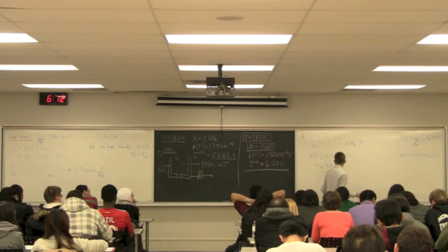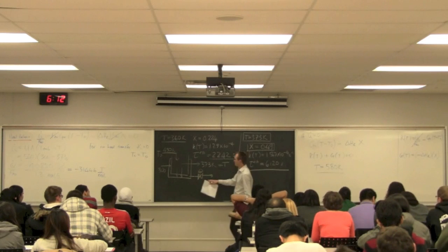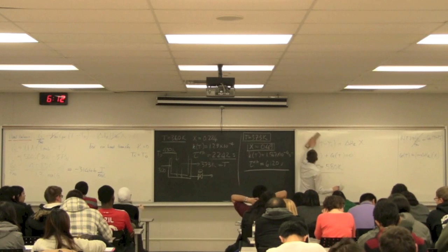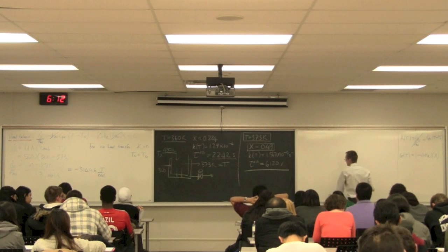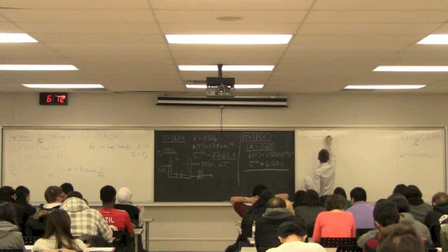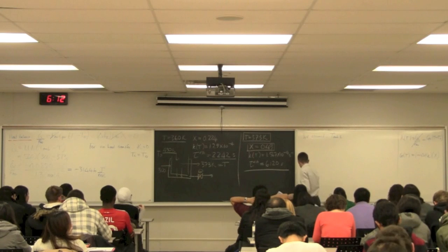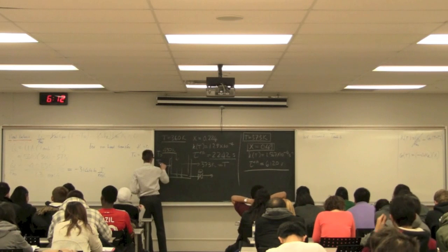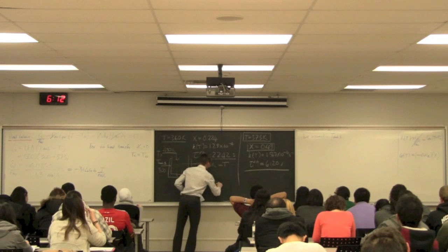The final thing I want to investigate here is the amount of coolant flow we need through this jacket. We made a fairly important assumption last time to derive that equation: we assumed that T ambient coming in, which we call T ambient 1, is equal to T ambient 2 leaving.